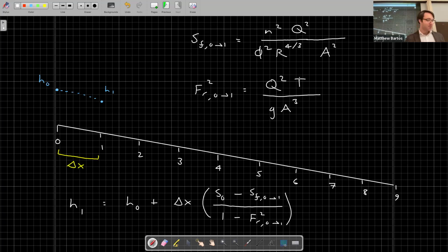So this is our first method for doing this. We're just going to use the previous point in sequence to compute the hydraulic radius, the cross-sectional area, the top width, and the cross-sectional area again. So there's a specific name for this technique. Does anyone remember what it's called? Yes? I guess in a way, because we are numerically integrating a function. I'm not familiar with that term being used for it, but it's possible.